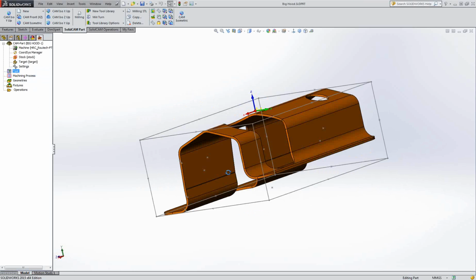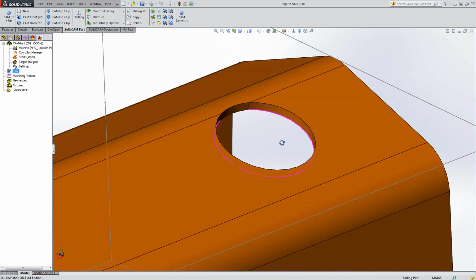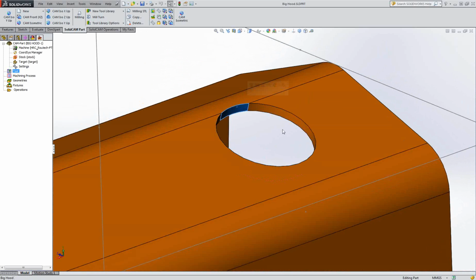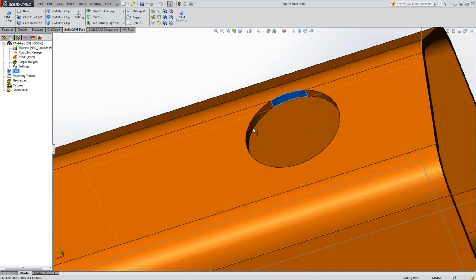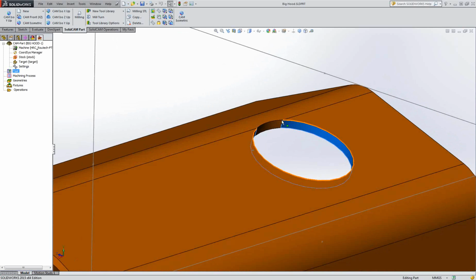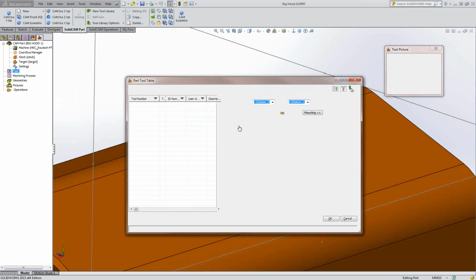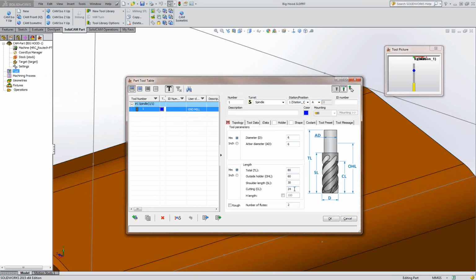So, what are we going to do first? Let's take this round hole here. We've got two distinct surfaces in there. We want to be perpendicular to this face, and we want to take this 5mm depth. Oh, sorry, it's 10mm. So we'll try and take it in 2 or 3 cuts. The tool that we're going to use, and we'll define that just now, is a 6mm burr.